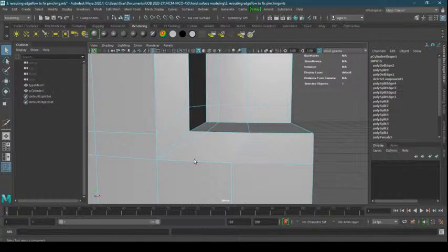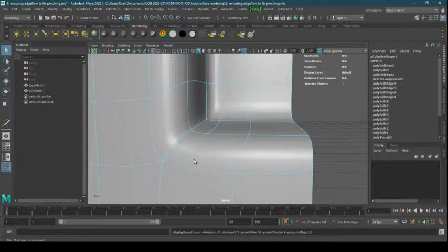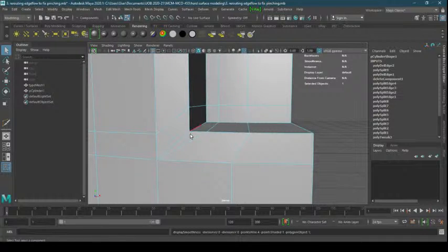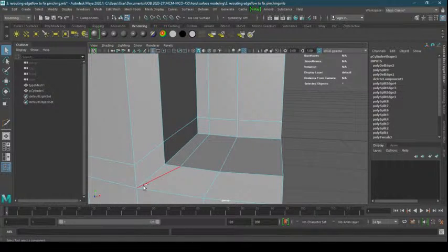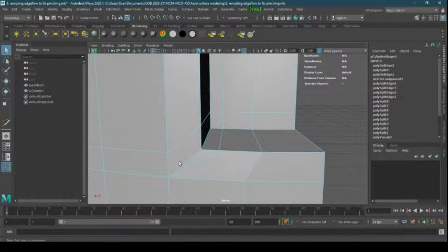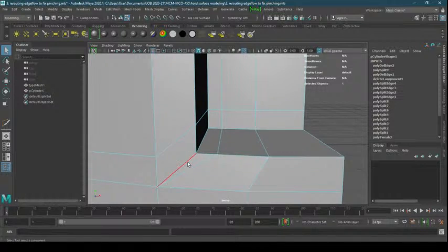Like we have done, removal of that part. If I press 3 on my keyboard, that's fine. But what I did here is I made a triangle, which is not right. We should not have a triangle. If you remember, I told you we should not have triangles. We should basically have quads, like squares, with all sides. So I want to convert this triangle into a square. The best way is to select this one, press Control on your keyboard, and delete it. That's all. It's removed.